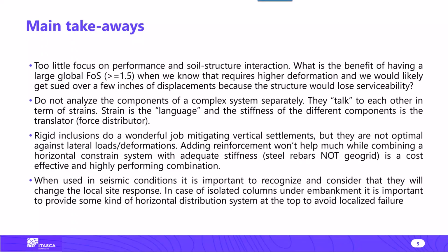In terms of rigid inclusion analysis, those are wonderful elements specialized for vertical settlement control. They tend to do a relatively poor job in the horizontal direction, unless some sort of mitigation or additional constraint is added to the system.